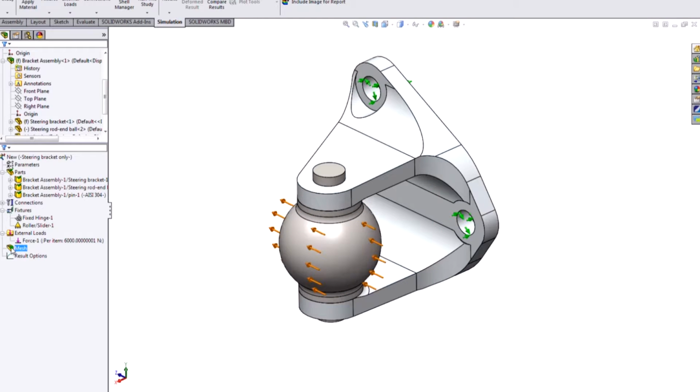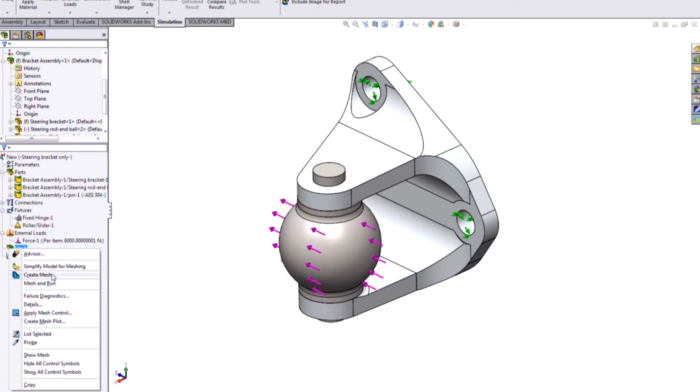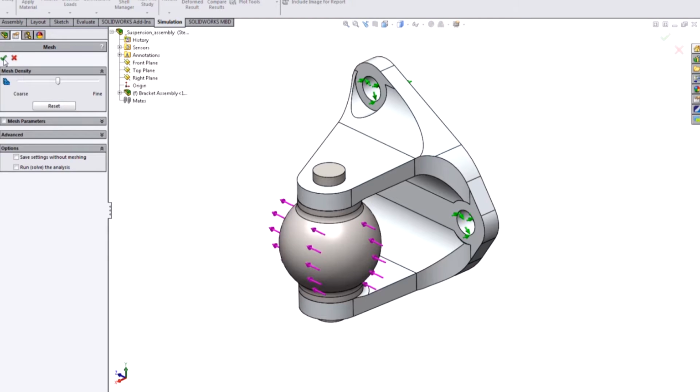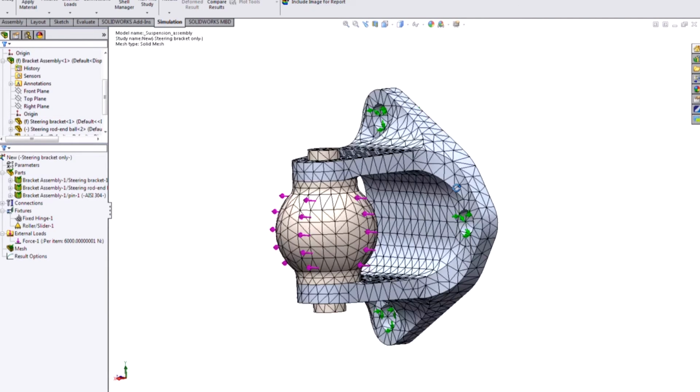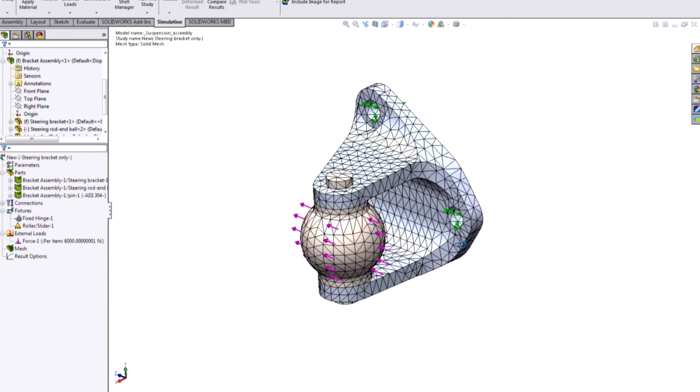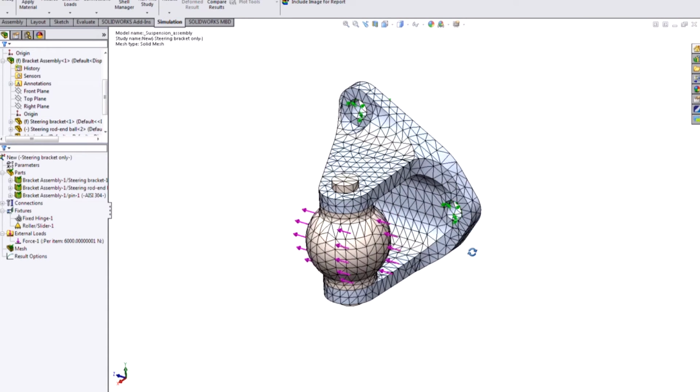All right, two phases the software is going to do for me, or let me help with, is to mesh the model. So for any finite element analysis, you're breaking the model down into a grid system. We use a tetrahedral grid, 10-node tetrahedral elements, and you'll see that it'll map to that automatically.